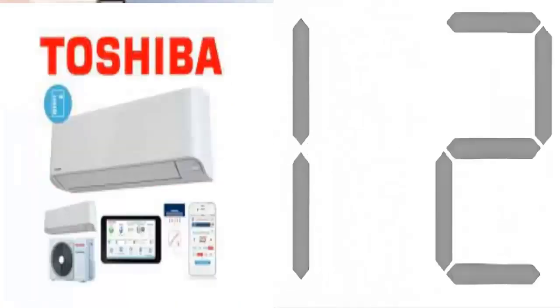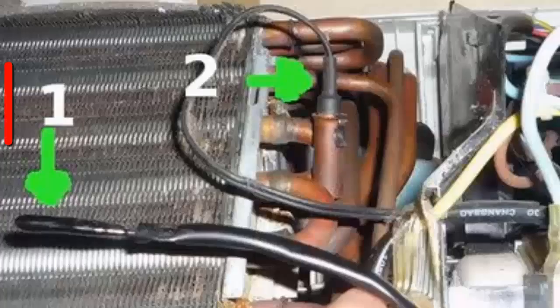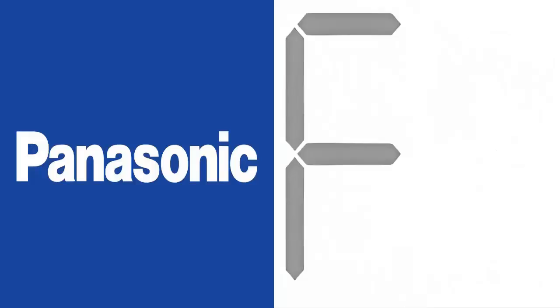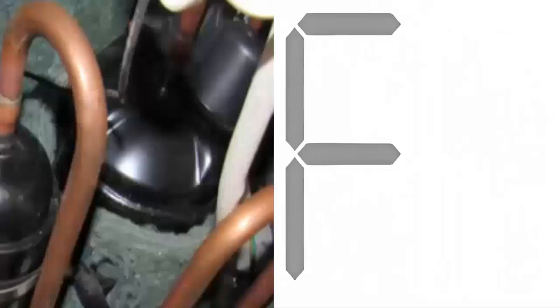3. For the Toshiba brand, the F12 error code refers to a problem with the evaporator coil temperature sensor. 4. In Panasonic units, the F12 code indicates issues with the compressor intake temperature sensor.